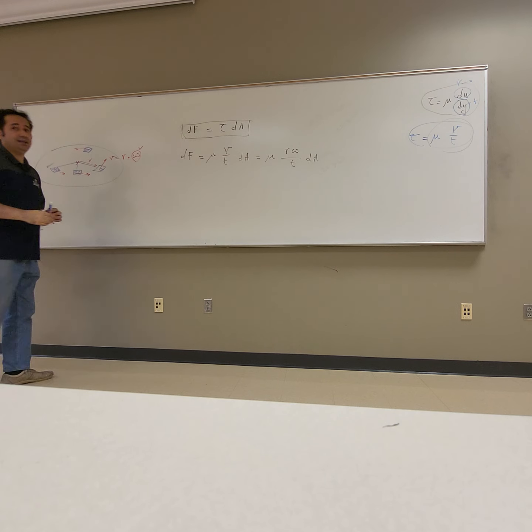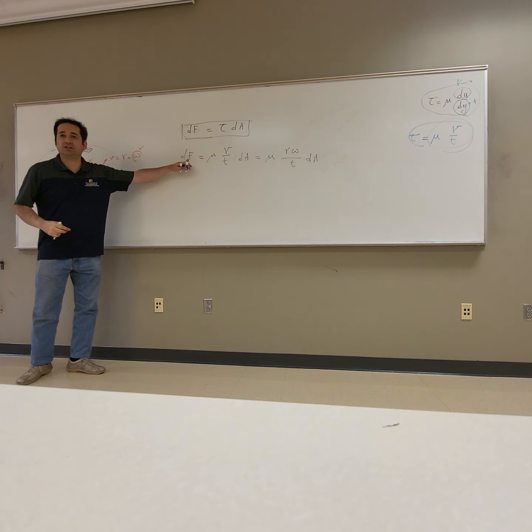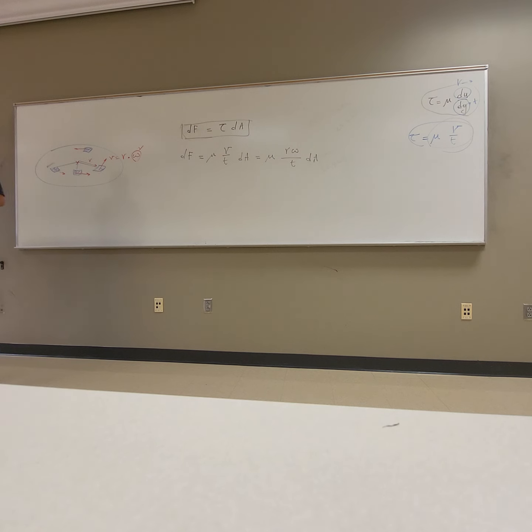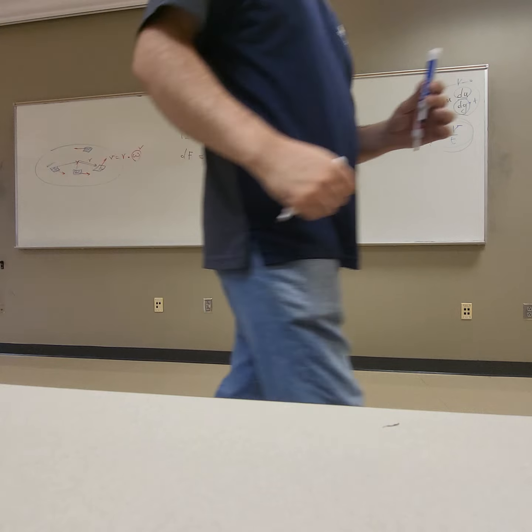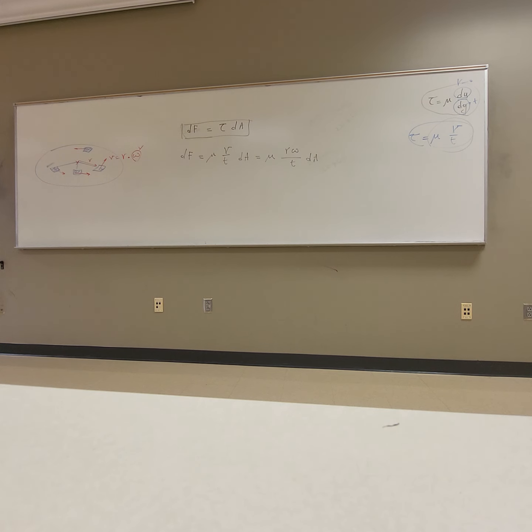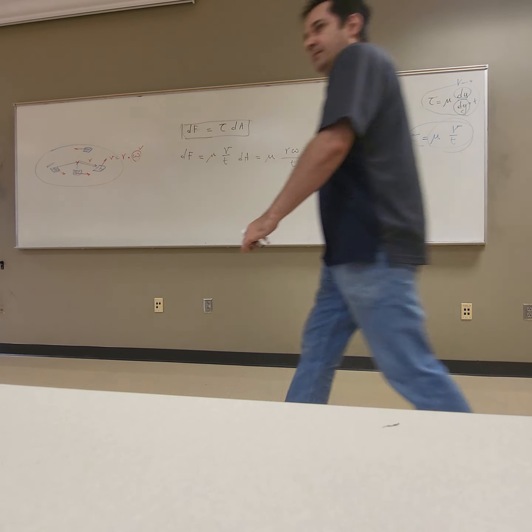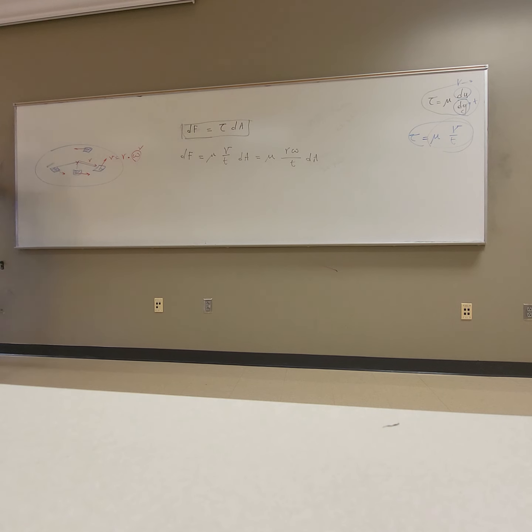So if I integrate all these forces, what do I get? Resultant force. You remember vector statics. F resultant is the summation of forces. And if I integrate all the little moments generated by this, I get what? The resultant torque, M, which is what my sensor is measuring.